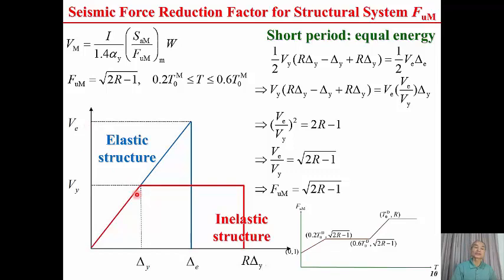If we allow the structure to enter into the inelastic range, and the ductility of the structure can be up to R, therefore the ratio of the ultimate displacement to the yielding displacement equals R, then we can just use Vy for the design of the inelastic structure. Therefore, we use VE for the design of the elastic structure, and we use Vy for the inelastic structure.